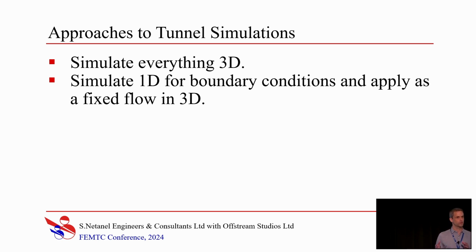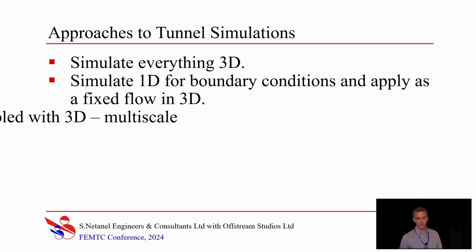But using those as boundary conditions is something that should be considered for a few reasons. First of all, those results are steady state. That means that I will not know how the flow field is ramping, and I am very interested in the transient phase. That's where egress happens, right? Secondly, because the flow is fixed in those vents, then I'm not going to get any reaction to changes in the flow field. And finally, if somewhere in the model the flow is not one-directional, then those results may not be valid.